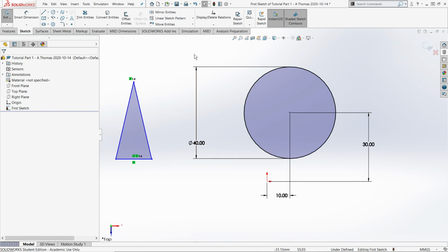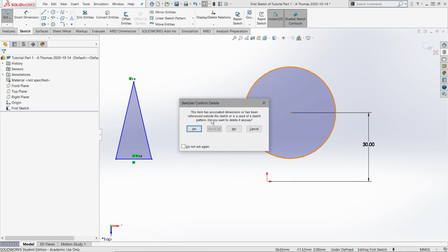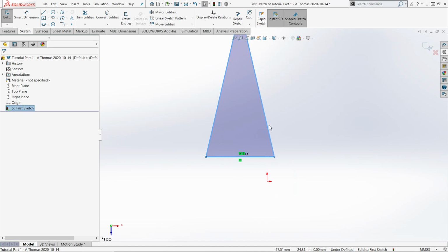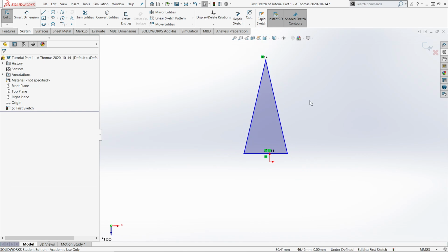So say I made that, right? And this is my sketch, and who cares about the circle? This is my sketch, right? And if I exit out of this and use this somewhere, sure it has the right dimensions now, but what's saying that someone doesn't accidentally open this sketch and scoot that over? So you need to fully define everything, otherwise, one, you can't build the part, and two, you could accidentally change it in a way that you can't really keep track of.